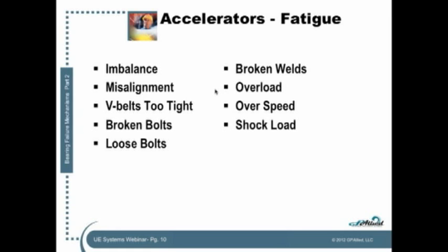Because if we're going to use our condition monitoring program to help us identify and eliminate root cause, then we can't just be looking for the bearing fault, because as you can deduce from this list, a bearing fault more often than not is not the problem. The bearing fault is the symptom of the problem.